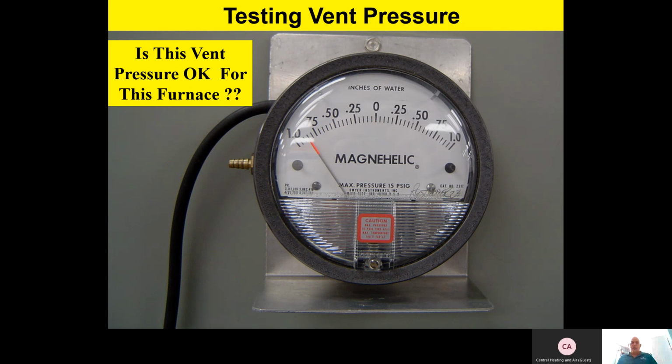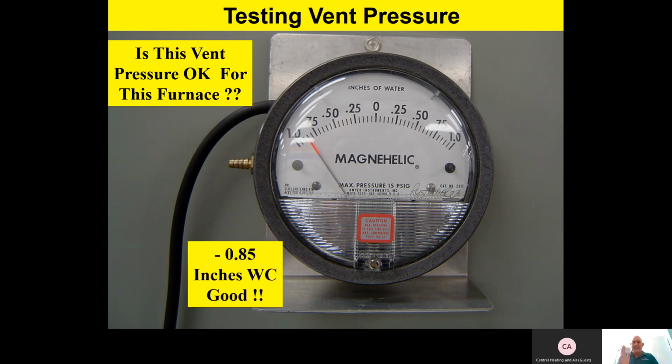Once you start the furnace, you're going to observe the vent pressure on that switch that you're testing. So you start the furnace and you let it go through its normal sequence of operation and let it start running normally, and then check the vent pressure. Now, team, remember, this is negative inches of water column. So in this first example, we have a negative 0.85 inches of water column.